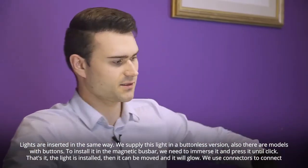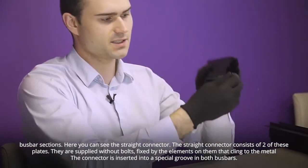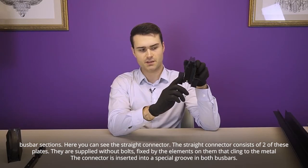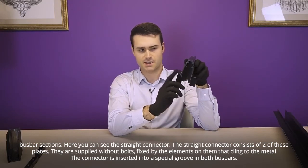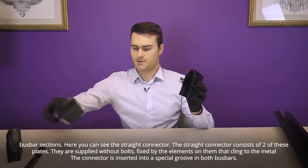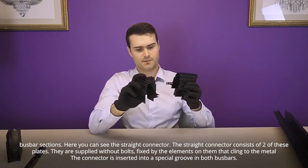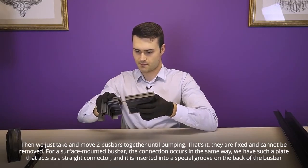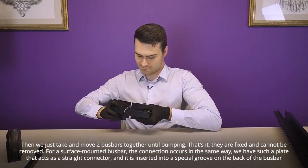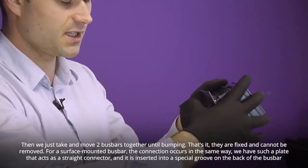We use connectors to connect busbar sections. Here you can see the straight connector. The straight connector consists of two of these plates. They are supplied without bolts, fixed by the elements on them that cling to the metal. The connector is inserted into a special groove in both busbars. Then we just take and move two busbars together until they bump. That's it, they are fixed and cannot be removed.